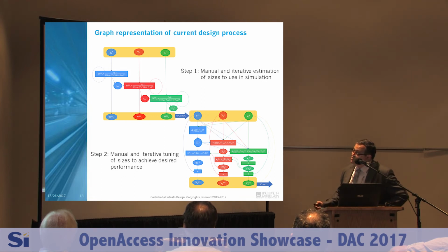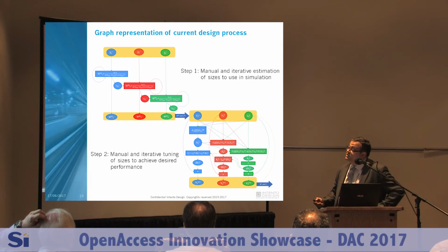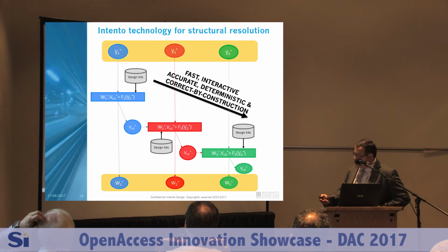computational effort. But the designer, in order to use the simulator, first tries to get an initial guess for widths and lengths. So he does something much simpler. He takes the first order model of the transistor, he computes a width, and then a polarization, and he moves to the second transistor and so on. So we thought about developing a methodology that can, based on this approach, which has a low computational effort, benefit from the accuracy of the simulator approach. So we have a fast approach with the accuracy of the other approach. So we did something simple. We adopted the same strategy as the designer.